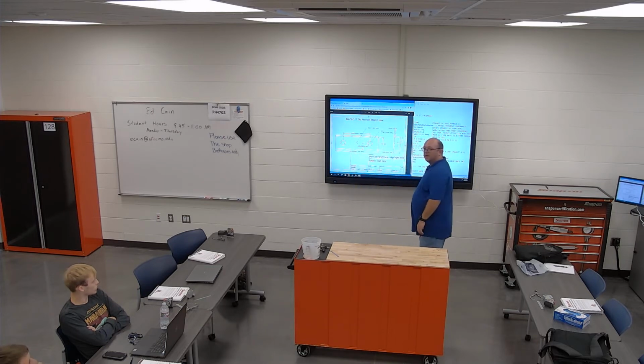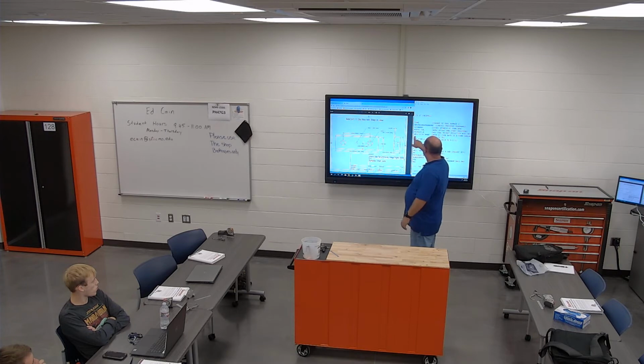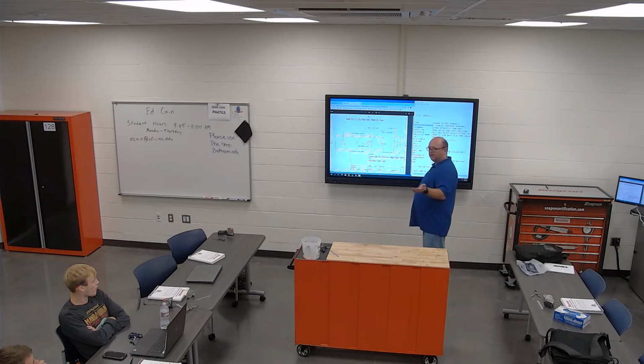I got a question. Uh-huh. Why does it say 0 when it's across? Because the top is Z0. I haven't looked at this program lately. Well, I guess it drops down right here. This makes more sense. So the first one's Z0, it'll just skim it across. That way you can see if it's wrong or not. And then the top of your stock is Z0. So if you take off 100 thousandths on your first pass, you set your offsets wrong somewhere.